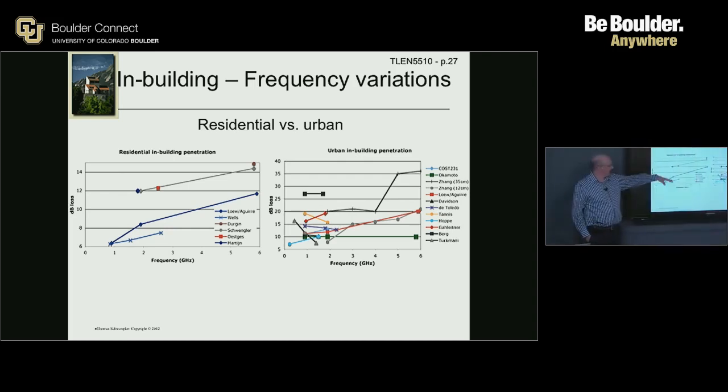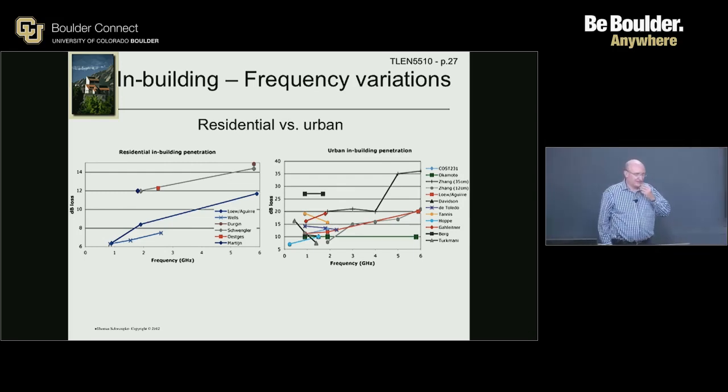But between one paper and another, things moved by 4 dB. So the uncertainty there is around 4 dB, and the value you measure is around 6 dB. So it's notoriously difficult to measure in-building penetration, and your method of measurement has a big impact on your results. So big, in fact, that it's a good percentage of your result.